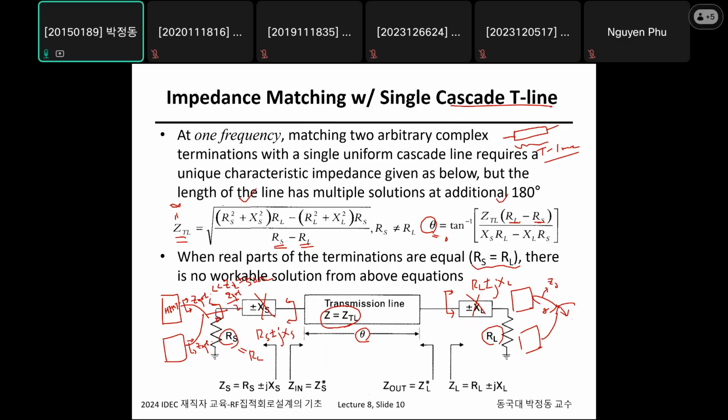For example, let's say this is 25 ohm, which is a half of 50 ohm, right? Or maybe this can be 15 ohm, which is much better than just trying to achieve a 2.2 to 50 ohm matching. Let's say the required optimum resistance is 5 ohm. Then if you just naively connect together, it becomes 2.5. This is too hard to achieve a match.